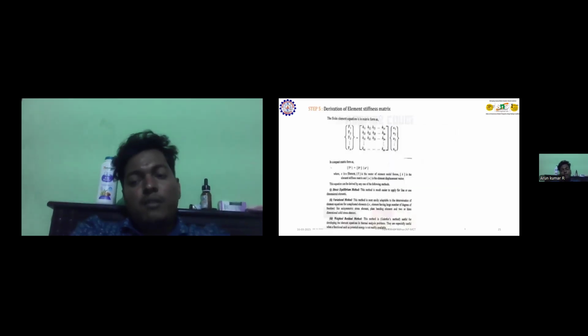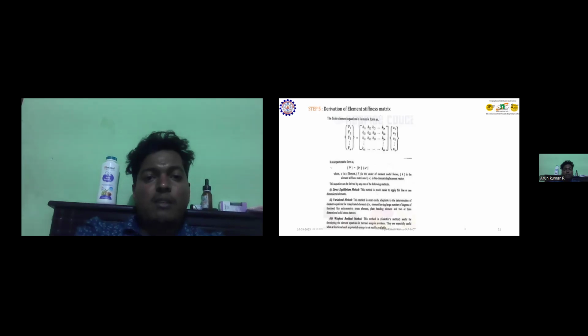The next step is the foremost thing for deriving the stiffness matrix, which depends on the application case by case. For example, if you are solving a one-dimensional problem, the basic stiffness matrix is AE/L times [1, -1; -1, 1]. We derive this by assuming a one-dimensional bar element, and we have to apply the boundary conditions. After forming the matrix, we derive the stiffness matrix equation.